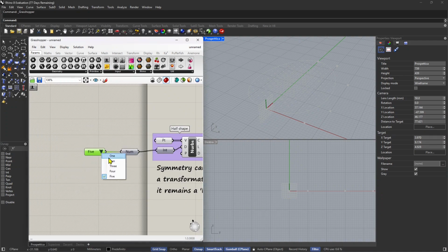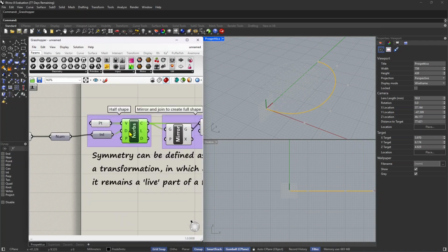And if I put this to 1, you can see this is not going to be a curve anymore. It's basically a series of straight lines with straight corners. So as soon as I increase this, it's going to make it more and more smooth. So it's basically the smoothness of the corners, which are defined by the points or the vertices.